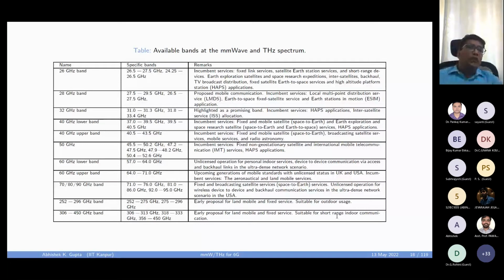Yeah, I have not actually looked carefully at these particular scenarios. My understanding would be that if you can get a line of sight somehow, it will work. The problem would be that you need to make sure to track the beam constantly. If things are moving, you need to move the beams, because this long distance communication with millimeter wave depends mainly on directionality. So if you can keep the directionality, things may work.